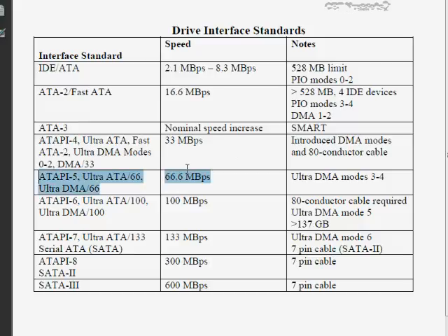These other ones are going to be more recent, although we're still going back several years if we're going to go to ATAPI 5. But with these, you can see that there's a speed increase as we move on up through the standards. Also, I want to point out that you see these acronyms change. We had integrated drive electronics, AT attachment, and then we went to ATAPI. What's going on here is it kind of settled on ATAPI as the official name, but before the actual standard of ATAPI 4, in this case, was introduced, the standard was kind of in beta, so to speak, or in testing phases, or the standard was actually written, but it was not officially ratified yet.